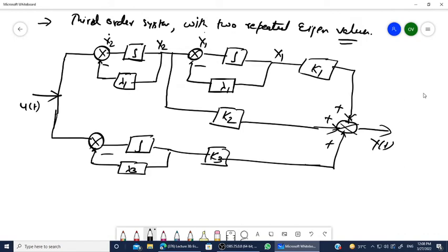So this figure is represented in the form of Jordan canonical form. Why? Because roots are repeated, or the eigenvalues are repeated, or you can say the poles are repeated. Okay. So from this figure, you can clearly observe that x1 is linked with the output, this state variable directly linked with the output. However, x2 is not linked.